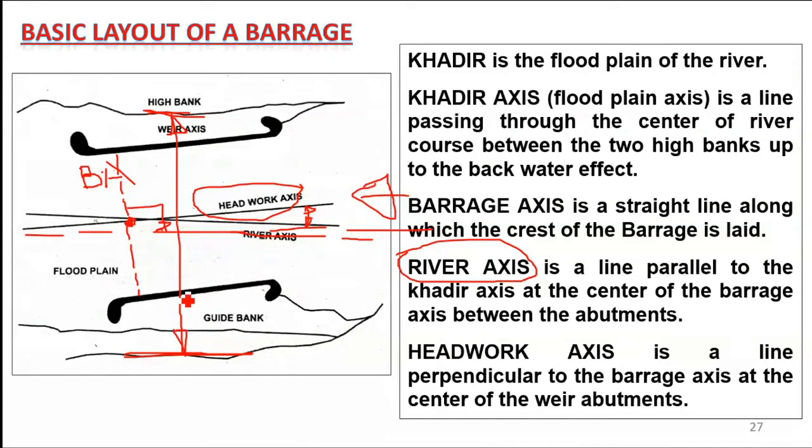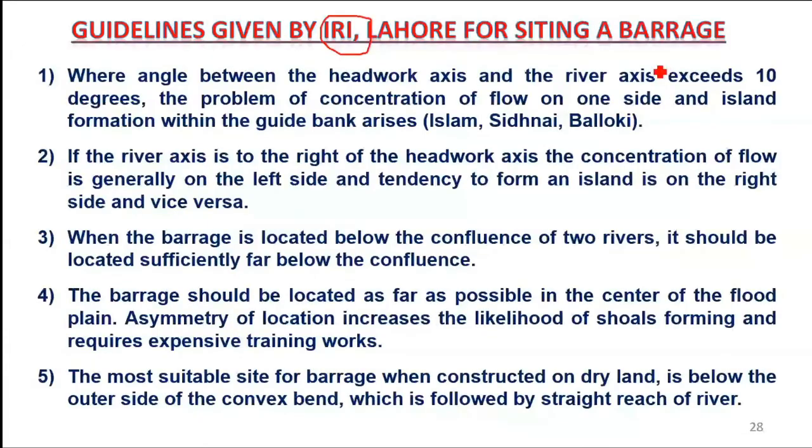When the angle between the headwork axis and the river axis exceeds 10 degrees, the problems of concentration of flow on one side and island formation within the guide banks arise.